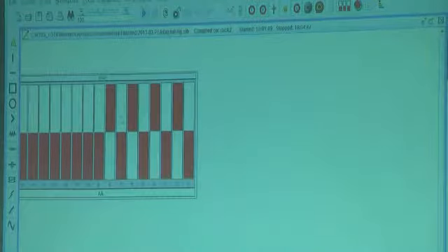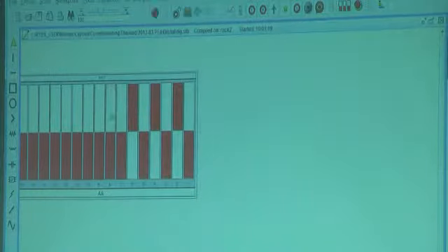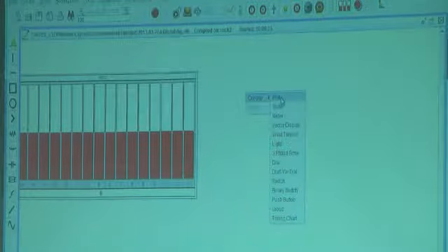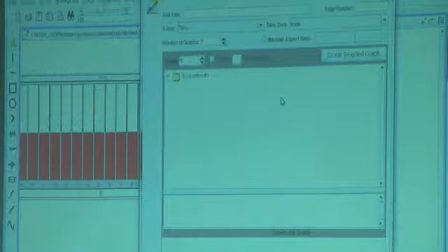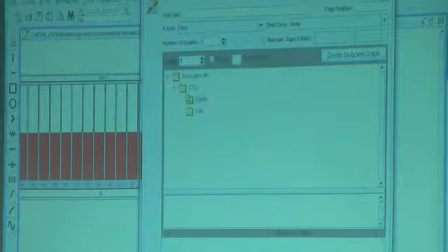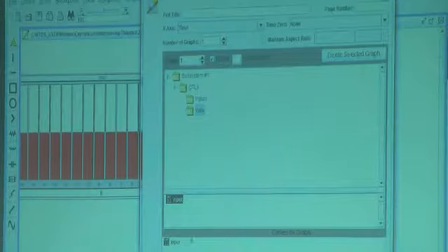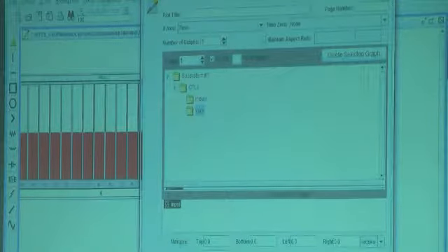So now at runtime, I'll create a plot to monitor the inputs. I'm going to make it a digital plot so I can see all the different signals. And then when I click down here, I can choose as bit pattern.